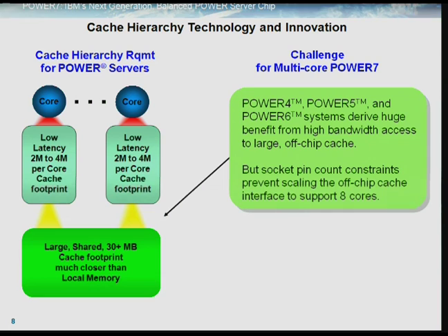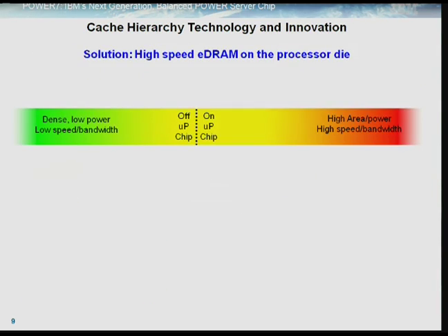Now the difficulty, though, as you go from Power 6 to Power 7, you might say, well, why don't I just throw another one of those tanks out there? Well, you really run into some bandwidth issues, because I would essentially have to take the large number of pins coming off the Power 6 chip to talk to the big cache tank chip, and I would need to multiply by somewhere in the neighborhood of a factor of 4. We're really good at, and I think we have a reputation, we throw an awful lot of pins at these things, but that's even a little extreme for something IBM's going to do in this space. So we need to tackle that one.